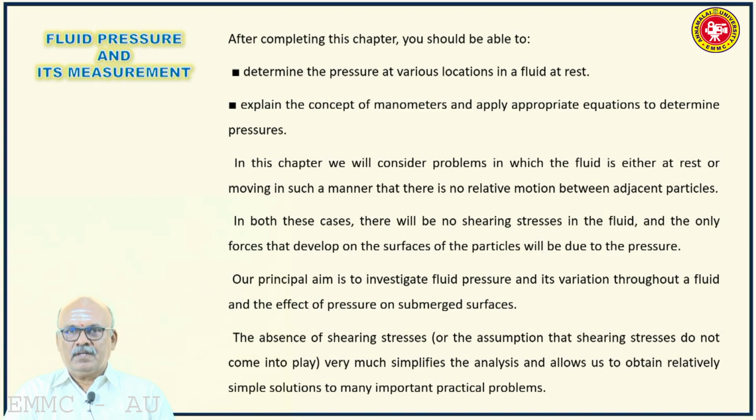So manometers are the instruments used for measuring pressure in a fluid. So when a fluid is at rest, it cannot sustain any shear force or shear stress, and the only force which acts on the fluid in addition to the self-weight of the fluid is the pressure, the fluid pressure.